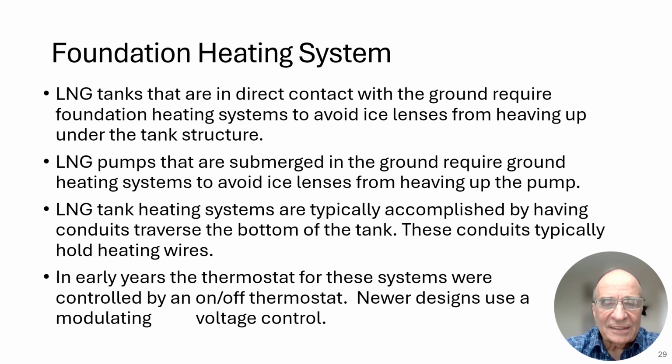LNG tank heating systems are typically accomplished by having conduits traverse the bottom of the tank. These conduits typically hold heating wires. In early years, the thermostats for these systems were on-off thermostats. Newer systems use modulating voltage control.